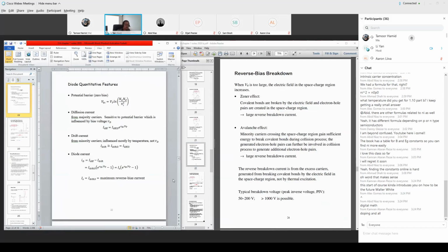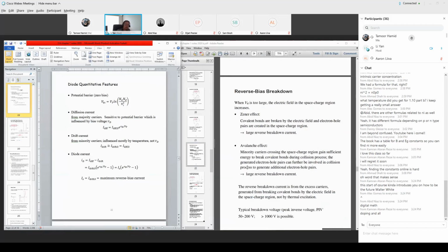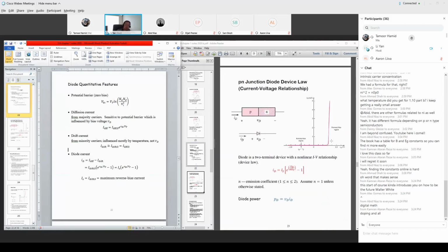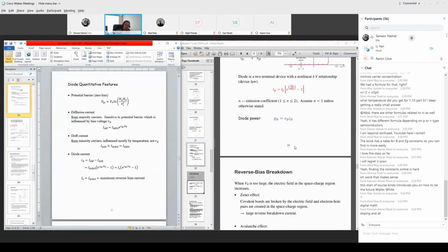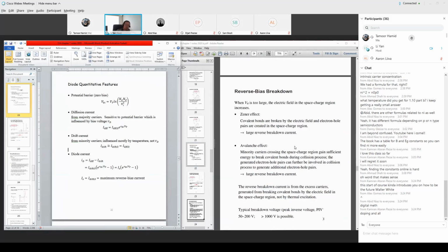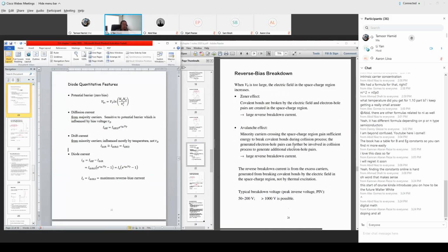So what that was saying is, the diode current we described on this side is contributed by the majority carriers, and on this side really by the minority carriers. All right? So far, still consistent with what we learned about what the majority carriers and minority carriers contribute, and which one contributes to which current. The reverse breakdown is a completely additional physical phenomenon.